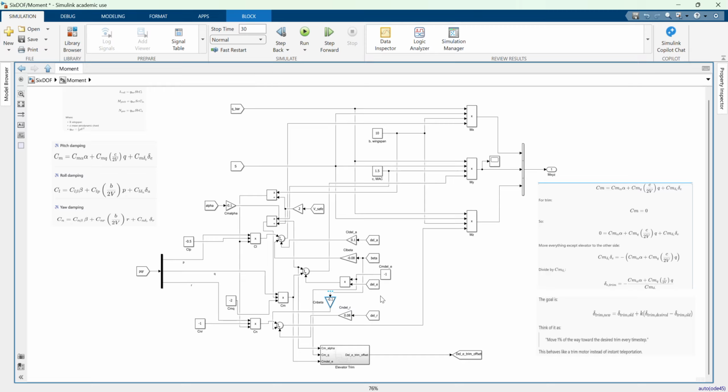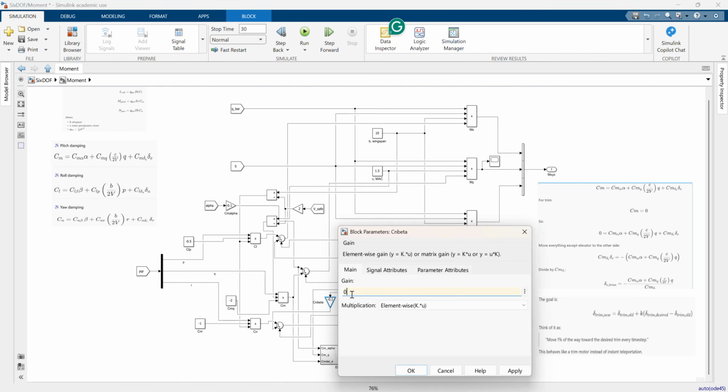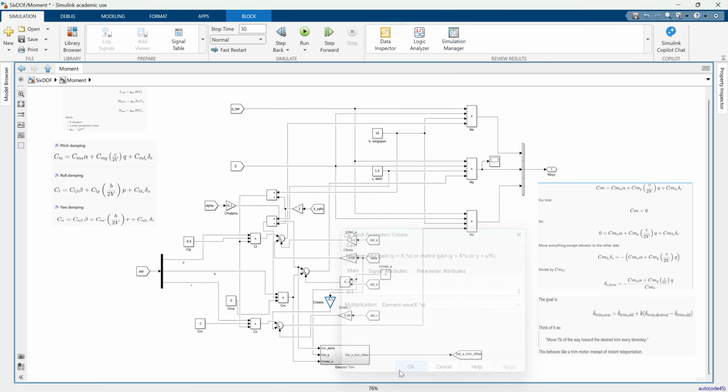And, oh, okay. So that should be a positive, because you want your airplane to yaw into the wind. A stable airplane would yaw into the wind, pitch into the wind, roll away from the wind. So with that being said, why don't we give that a run? So here is my Euler angles plot.